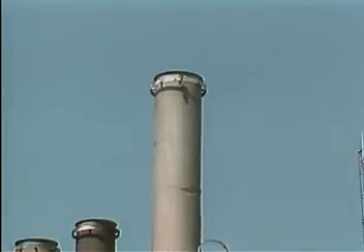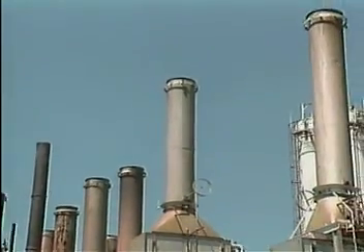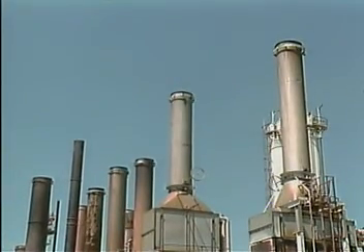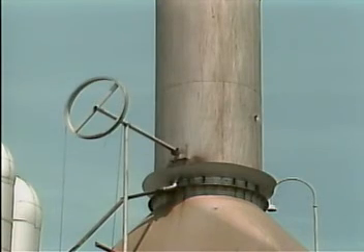In a natural draft furnace, the height of the stack affects the amount of draft that can be produced. In general, if all other airflow conditions are equal, the taller the stack, the greater the draft. This is because a taller stack creates a greater difference in pressure. Often, the amount of draft must be adjusted for proper operation of the furnace. Since the height of the stack cannot be adjusted, another technique is used.